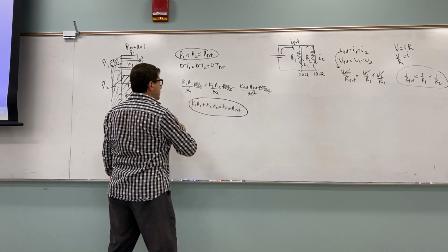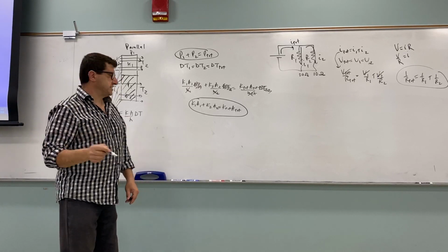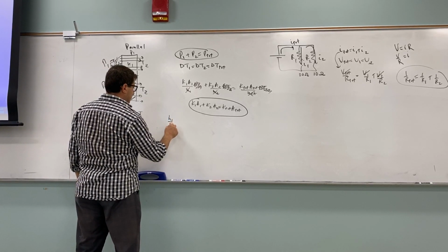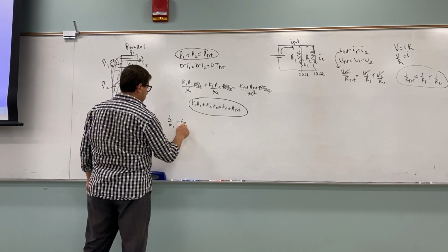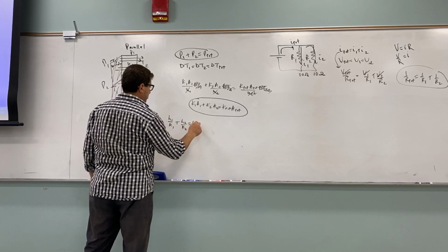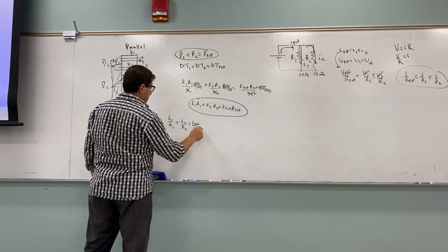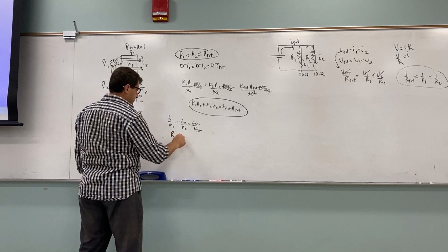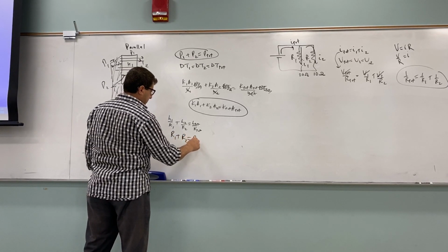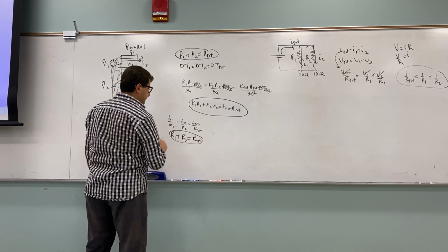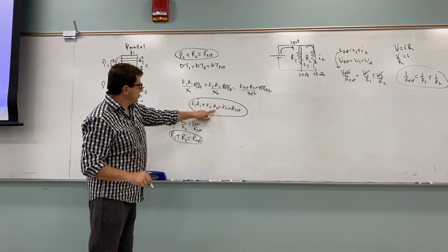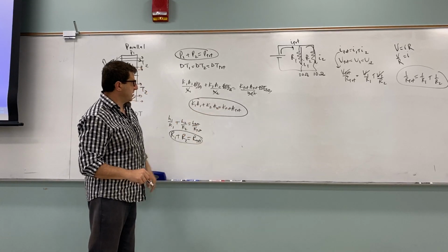So the conductivity, the way that they added in series was the other way, right? It was H1 over K1 plus H2 over K2 is H total over K total. And then I substituted, this became R1, and this became R total. So this one ended up being K1A1 plus K2A2 equals K total A total.